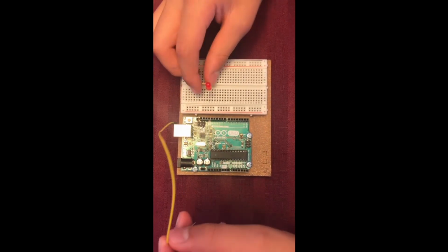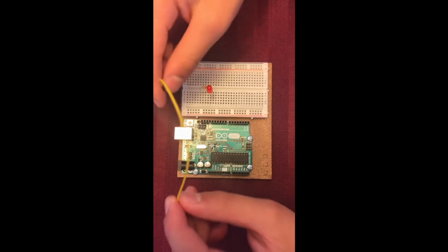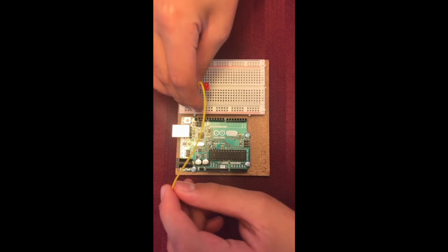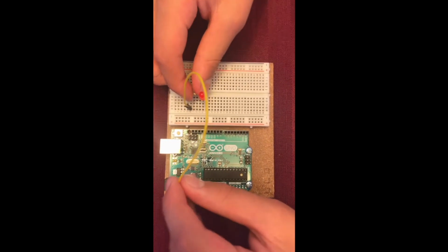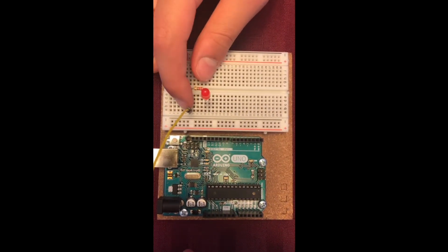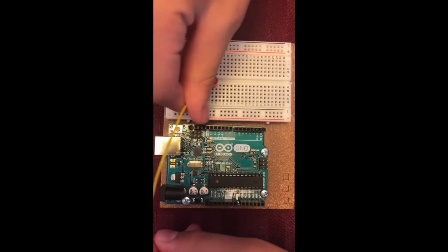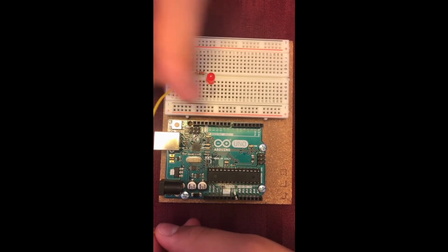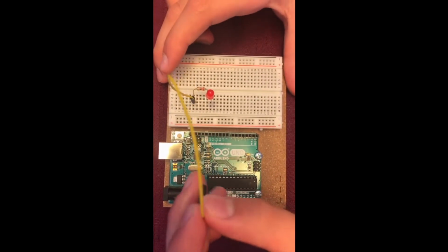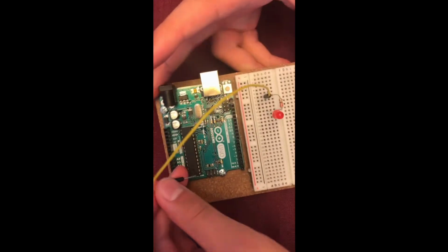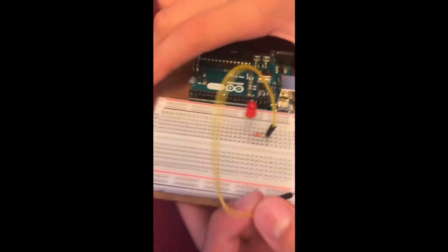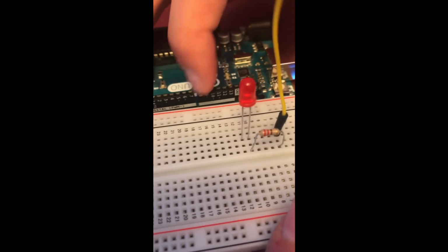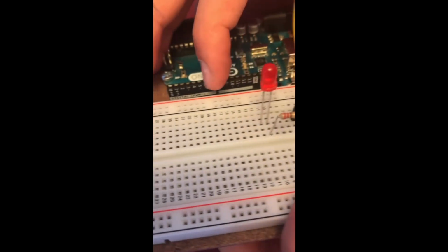So now you have a resistor. Connect the other leg of the resistor to the jumper wire, so they're connected vertically, as you can see. Doesn't matter if I put it here; they're connected vertically. So just want to show you, connected here. And this one actually needs to be connected to pins. So yeah, as you can see, let me show you the pins on the Arduino. It needs to connect to one of these pins, sorry,